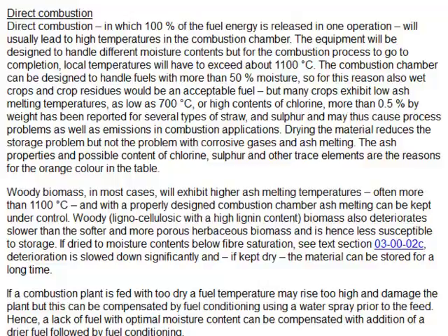Now, combustion chambers can be designed to handle dry fuels or wet fuels or moist fuels. And typically, we can say that a dry fuel is a fuel where the moisture content is like 20% or less. A moist fuel is a fuel where the moisture content is about 20 and up to 40%. And a wet fuel is a fuel where the moisture content exceeds about 40%.